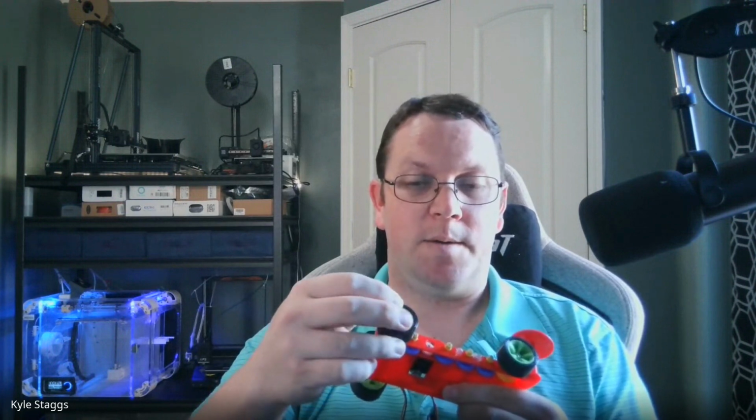top speed. I forget what the actual effective speed should be, but it should reach a scaled speed of something well in excess of a couple hundred miles an hour. So it was designed to be very, very fast top end. But these motors just don't have enough torque. So I would need to have 4 batteries and 2 of those motors minimum. And even then, I don't know if that would be enough to actually drive it forward. So there's tons and tons of design considerations for this.